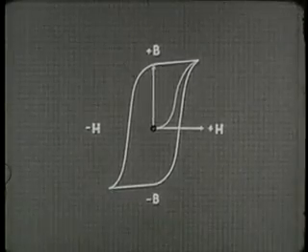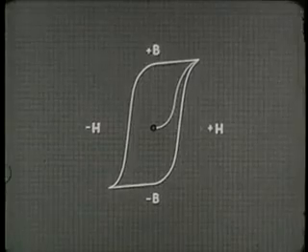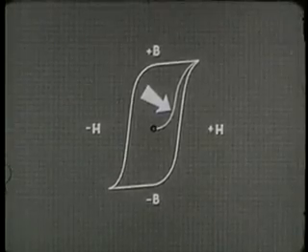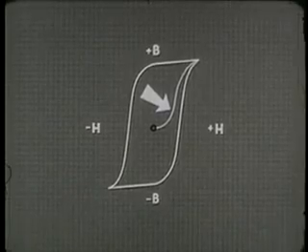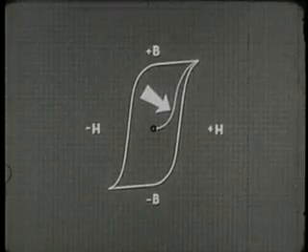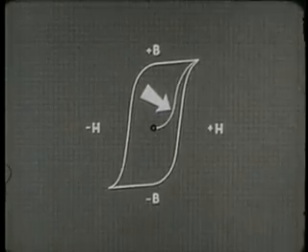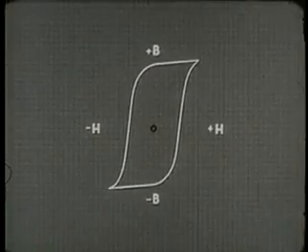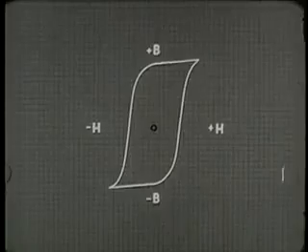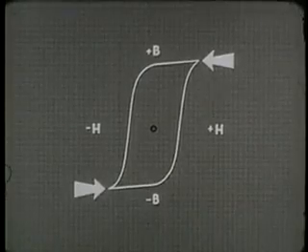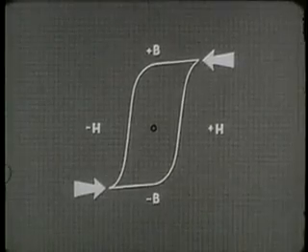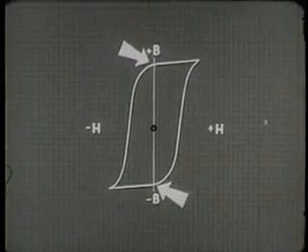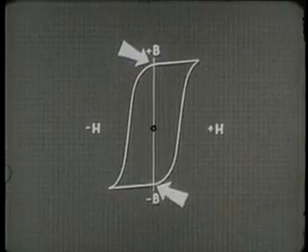We have now plotted the positive and negative magnetization of a core. The original S-shaped curve is produced only when we are first magnetizing the core from a completely unmagnetized state. From then on, we're concerned only with the rectangular loop, which tells us the limits of saturation that can be reached with dot and non-dot current. Also, the amount of magnetism that will remain in the core after the current stops.